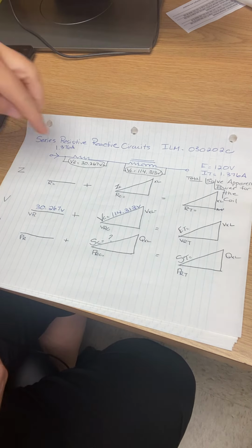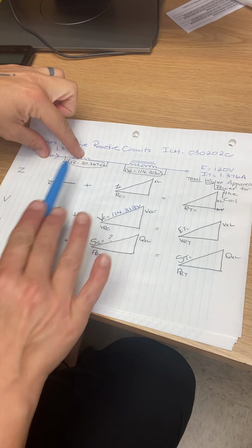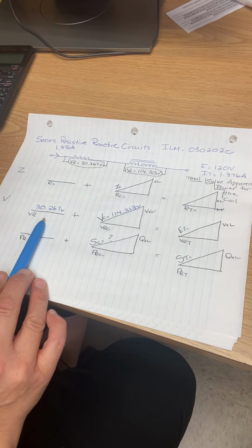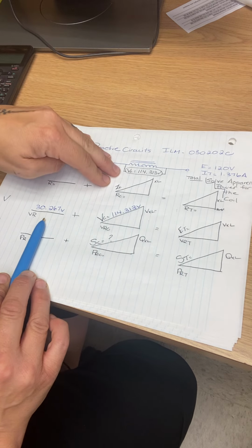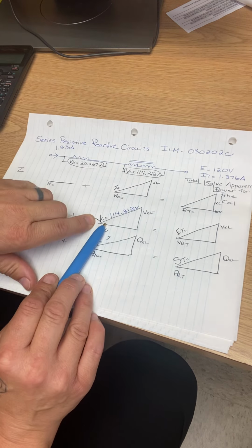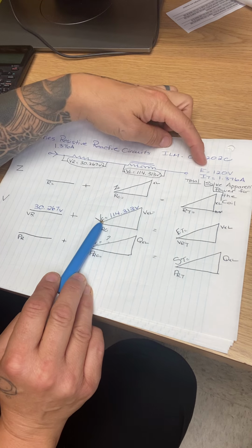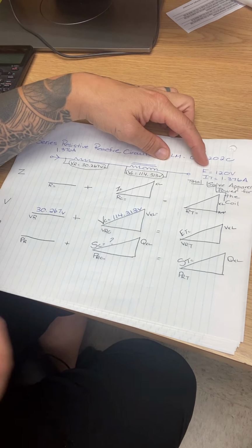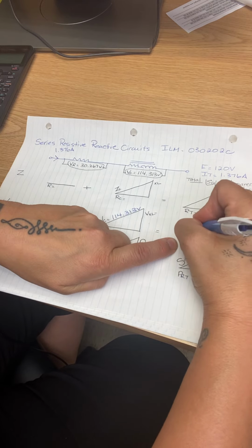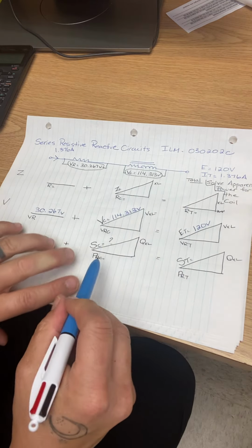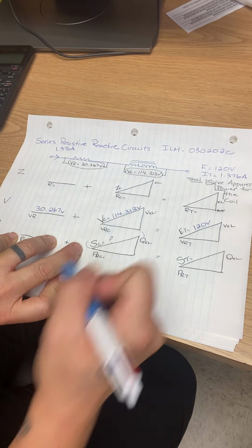Okay, so right now I took the volt drop of the resistor and I populated it in the volt drop for the triangle. For the resistor. The volt drop for the coil is the hypotenuse of that triangle. They also did give me the voltage for the entire circuit, right? So that is always the hypotenuse of your circuit total. And that might be useful in us trying to find the apparent power of the coil.